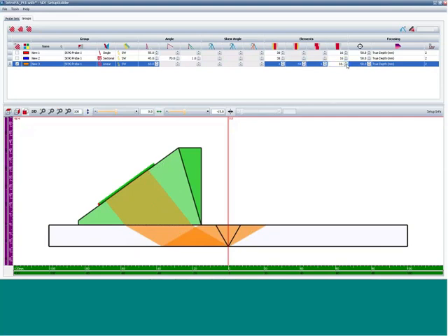So the size of each of those A-scans or beams is the conventional equivalent of a 5 megahertz, 10 millimeter conventional UT probe, but I have an A-scan every 0.6 millimeters across the entire array.